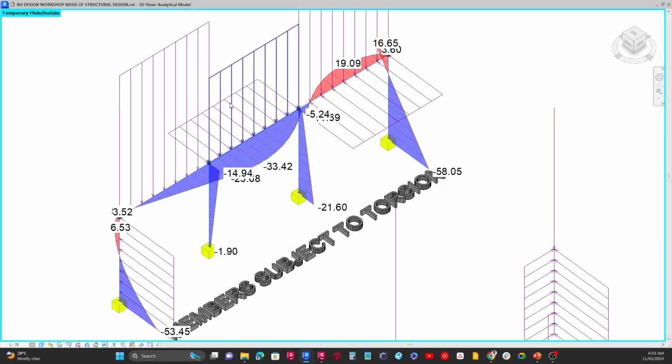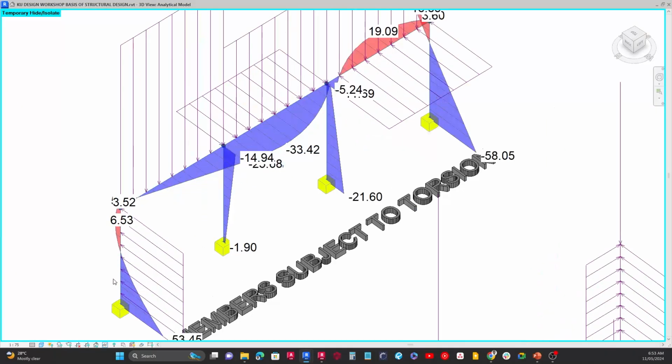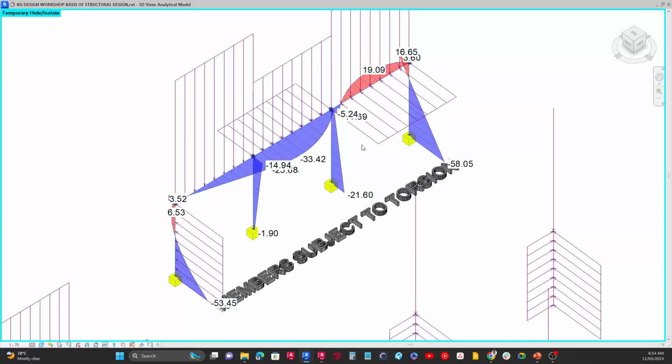All right, good. So you can see here that this load here in this direction is what causes this bending in this direction, and this one coming in the opposite direction on this span here is what causes this one over here. Likewise as well, this load here on this column is what is causing this, although this isn't torsion, but a combination of all of this on this column can actually cause what we call torsional buckling on a column, right? And we'll talk more on that when we get into the design aspect. So a combination of all these loadings is vital.